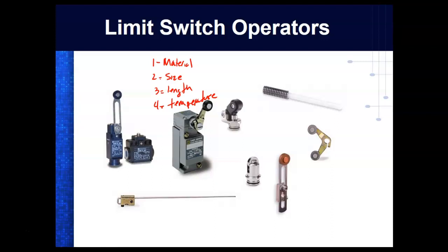Thermocouples, you have to run the exact wire, whatever the thermocouple is, that's the wiring you have to run all the way to the gauge. So our jet engines had a loop around the combustion chamber, a thermocouple. They monitored that combustion really, really well in that jet engine. And we had a wire that broke off one of our thermocouples. And we went out there, we didn't know this, even though we were electronic. And we got a regular old splice terminal, stripped it off and put a splice terminal on there, spliced it back off.